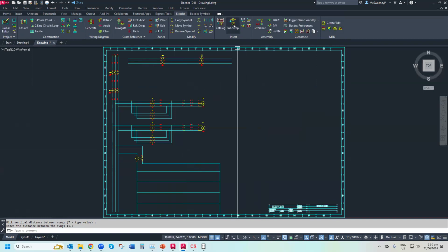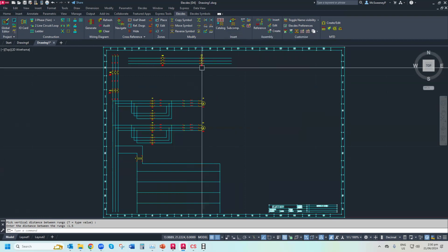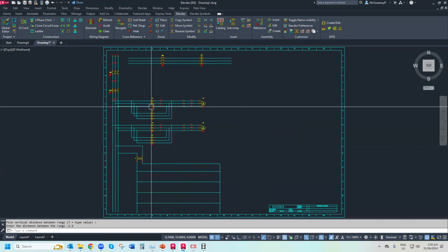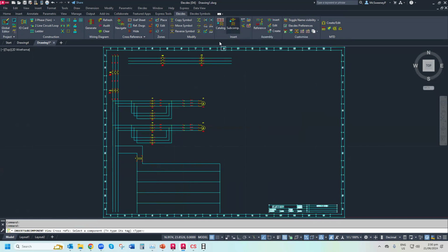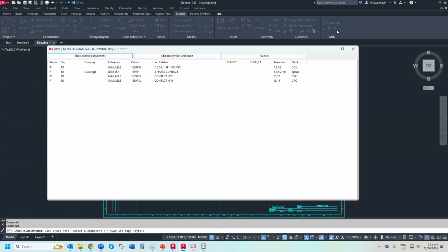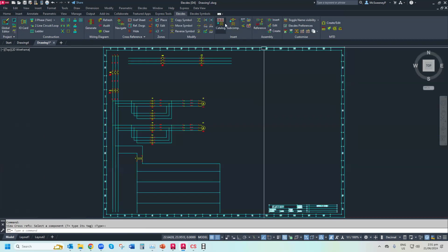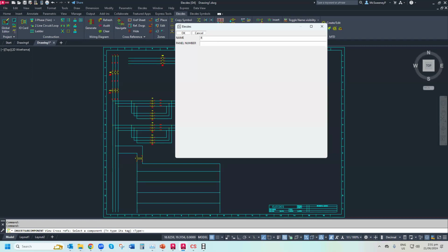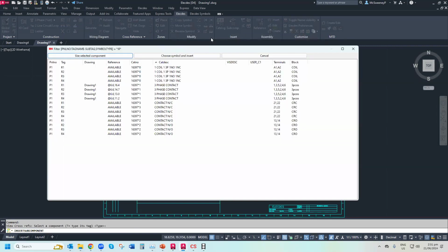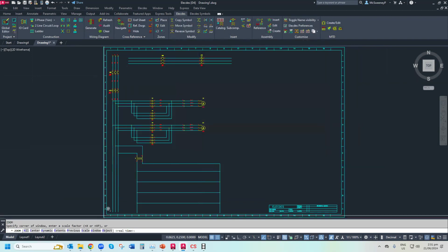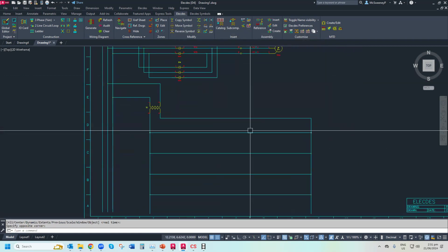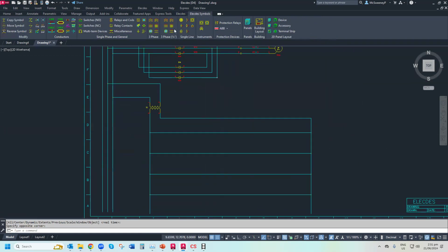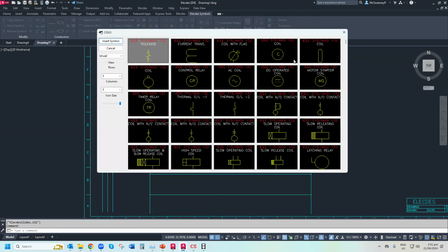All right, now again, other things that make drafters and engineers go, that's cool. Insert subcomponent. As I say, relays, that's got 3-phase contacts, a coil, normally open, normally closed. Subcomponent, I could click on that and it shows me what I've used, what I haven't used. But again, I might be on sheet 500 and I can't remember, where you can just right click with your mouse. I know they're all called something or other, star, wildcard, shows me what I've used, what I haven't used. But as I always point out to people, there's more than one way to skin a possum, flexibility being our middle name. I can go back into symbols here and also manually go and find relay and other coils.